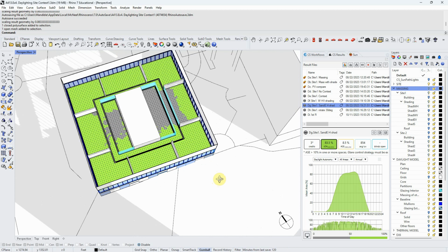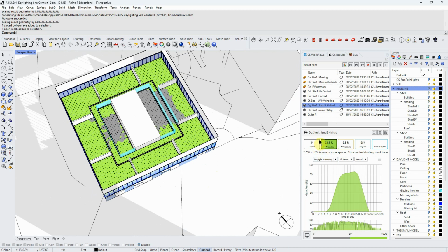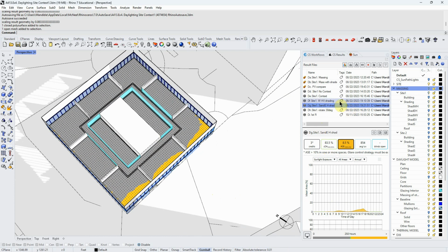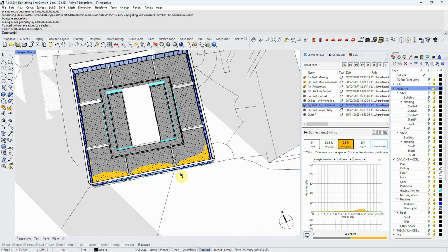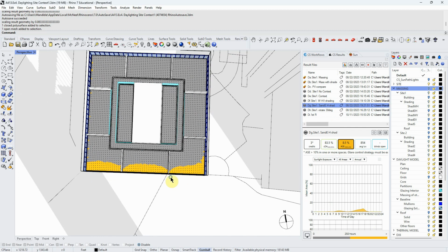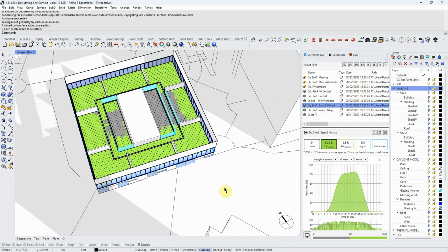And the metrics we were thinking about were LEED 4.1 related, but that's just a certification. Really, what we were saying was, do we have enough lighting, spatial daylight autonomy, and do we have too much in some places? And of course, we start off with way too much, and then we usually are able to make some decisions quickly to get us more in line with the goals of the certification and of having good daylighting in the space.